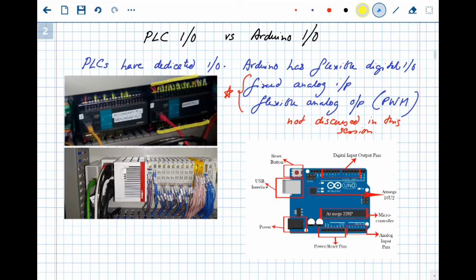On modern PLCs, on the other hand, nowadays I use modular PLCs quite a lot. The PLC is basically what you see on the left-hand side, the box part I just did. But depending on the requirements, you can buy boxes. So if you do not have requirements for inputs, you don't buy those boxes. So what you see over here, there are multiple boxes. The first four over here are basically drives. They are compact drives. Then we have safety terminals, and then there are inputs and outputs.